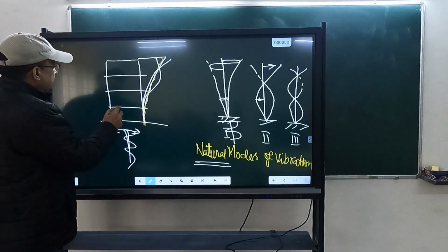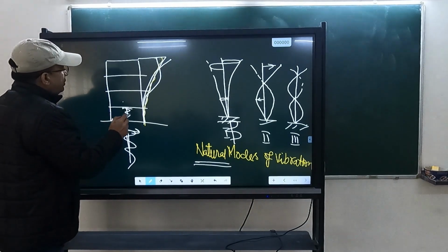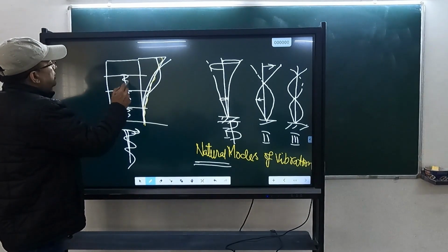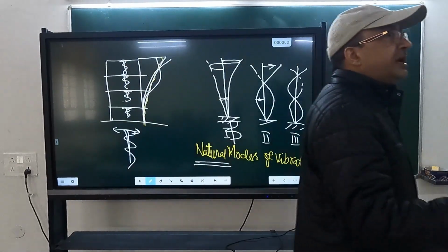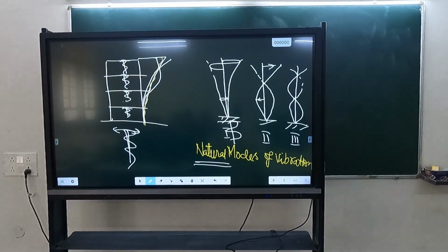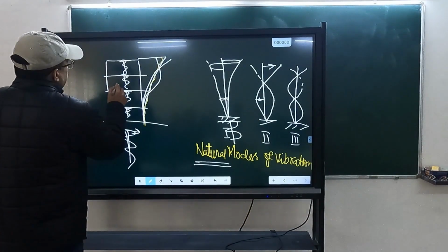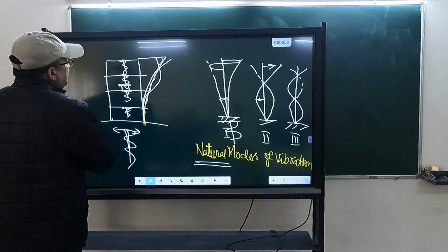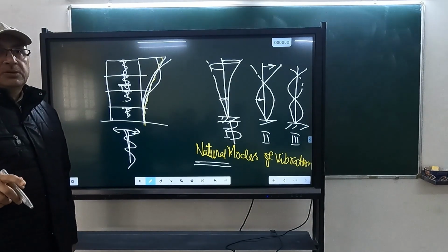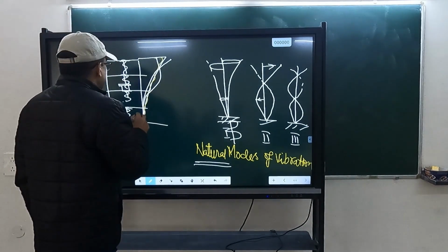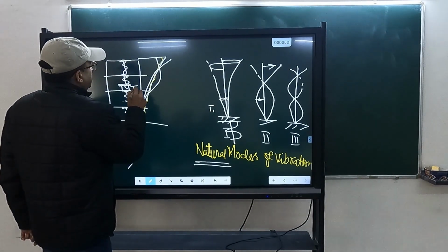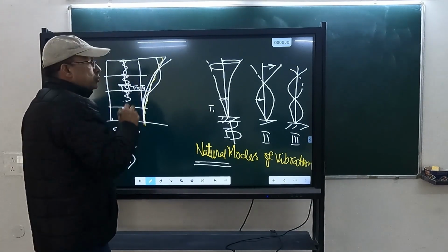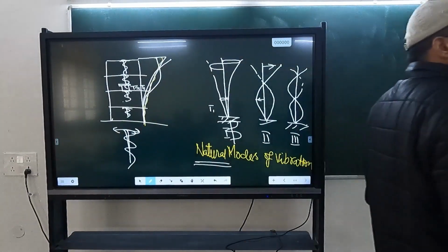When the ground motion is passing through each floor, it will get amplified, and at the same time there will be filtering action. Those non-structural components, those equipment which have their frequency close to the fundamental frequency of the structure, if this also has a period close to T1, what will happen?